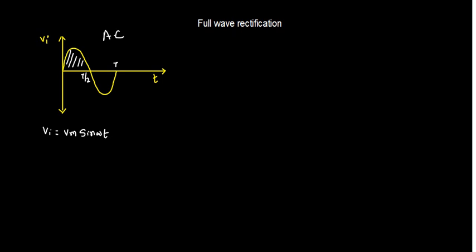The conversion of AC to DC that is done by the full wave rectifier is called full wave rectification. So here we are going to see the circuit of the bridge network, or you can say bridge rectifier. Let me draw that bridge rectifier circuit using diodes. It's a very simple circuit. On this side I'm going to draw a square, and in that I'm going to add those components. The main key component is nothing but a diode.